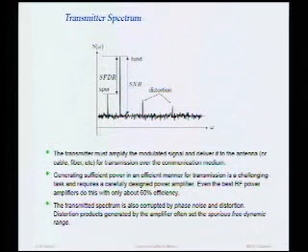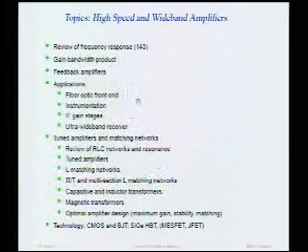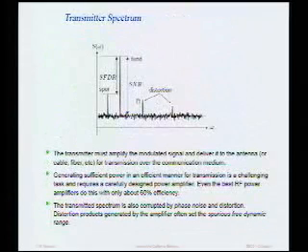So here, our power amplifier, even though it's designed to be linear, generates what we call harmonic distortion. Harmonic distortion is energy at the second harmonic. So if this is frequency 1 gigahertz, we find there's a tone at 2 gigahertz. We also find there's a tone at 3 gigahertz. That's the third harmonic, and so on and so forth. And why are these tones bad? Who cares? Let's just transmit them. Why do we not want to transmit these tones?